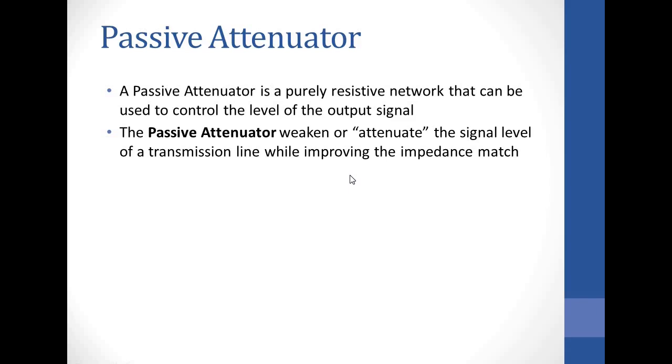On the issue of impedance matching, an attenuator should always have a certain input impedance that is known. If the input impedance is 600 ohms, you can easily connect a 600 ohm signal to the input of an attenuator with correct matching.